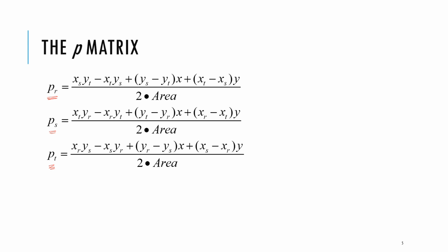With this PR, PS, and PT, I can find the temperature at any location XY from the 3 nodal temperatures, and this is basically my interpolation function.